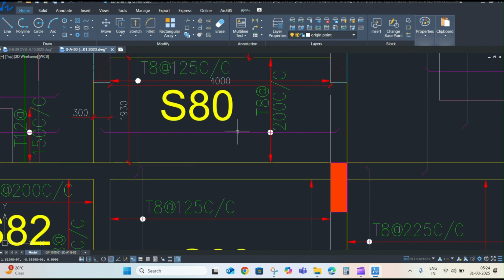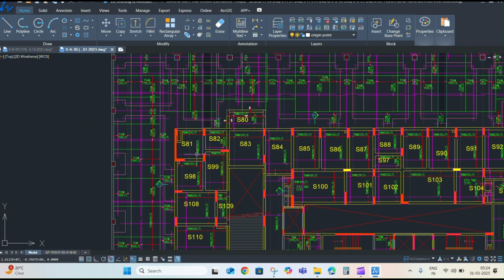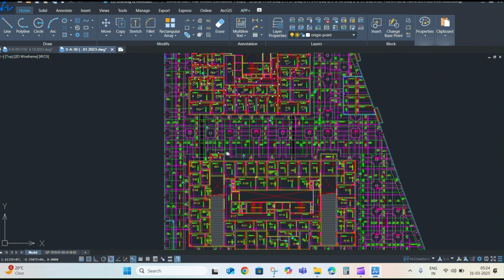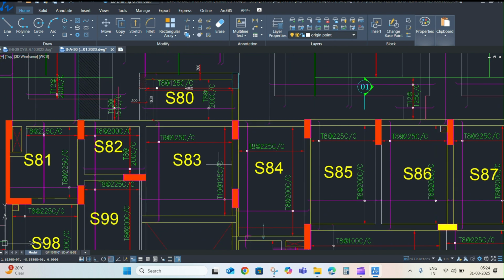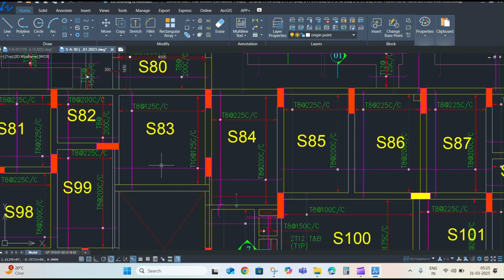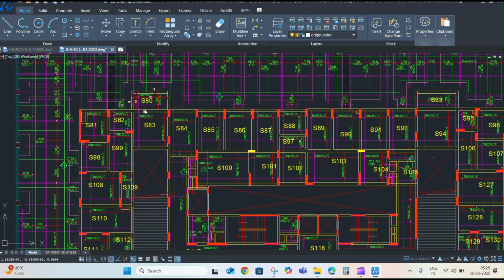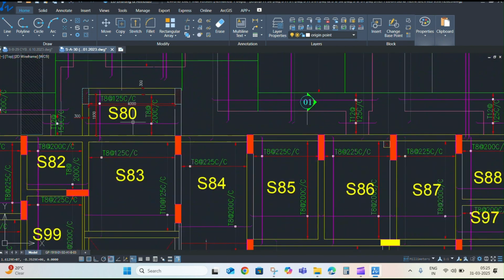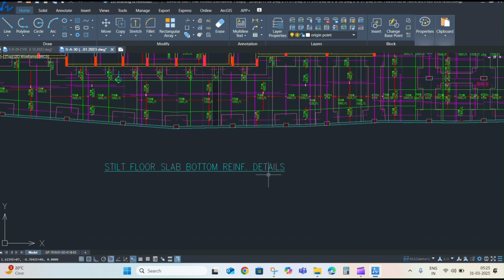Creating a structural plan in AutoCAD. Start with the layout of the floor plan and position the structural elements: beams, columns, and walls. Add annotations for dimensions, material specifications, and details. Use the XREF tool to incorporate other related drawings, like architectural or mechanical drawings, that integrate with the structural design. Ensure everything is to scale and accurately represents the real-world layout.